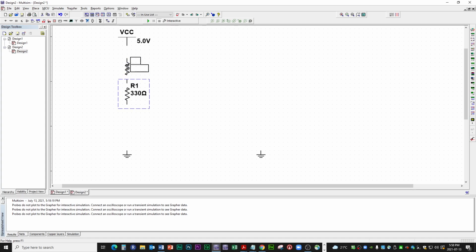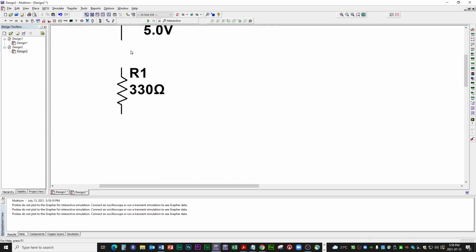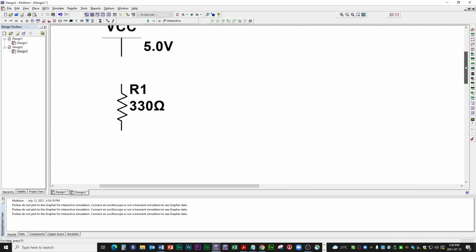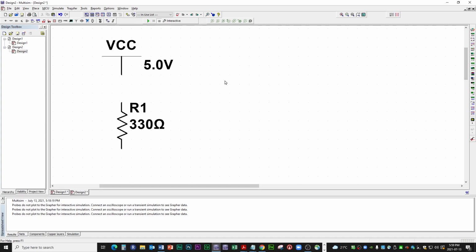We can move the resistor up a little bit and connect it. How do we make connections? I'm zooming in. I just have to use those sidebars here to move the view around. If you mouse over that here, see the dot appears, because the grid is employed. I'm not sure if you can see it on the screen or not.